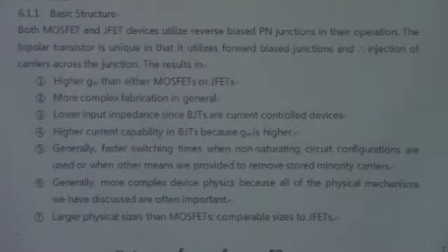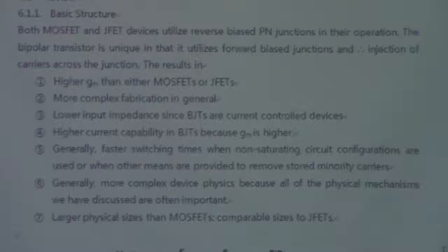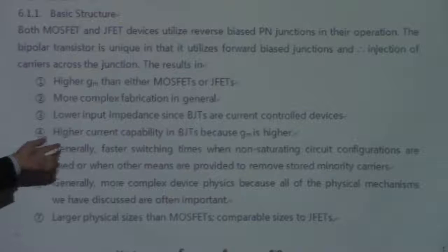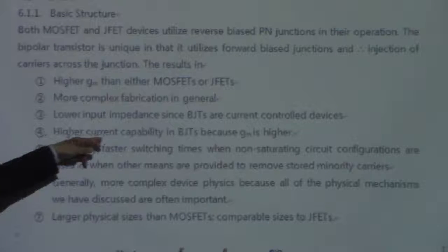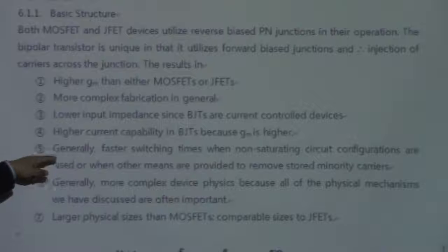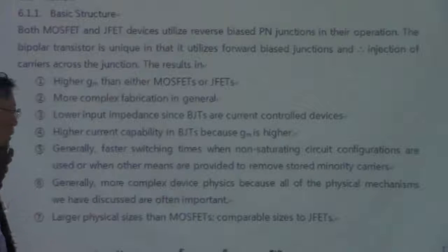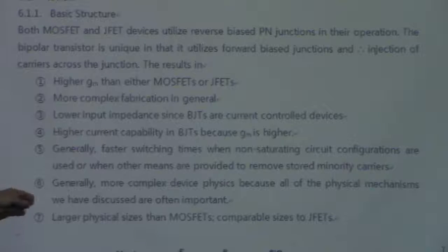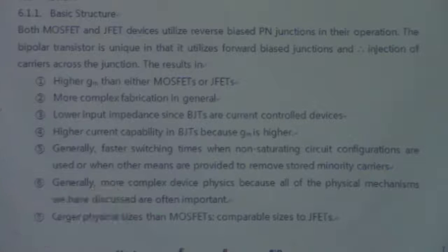Higher current capability in bipolar. Bipolar transistors are usually used for the protection circuits for input and output because they have the capability to endure high current. And generally faster switching times because it deals with the high current, and generally more complex device physics.